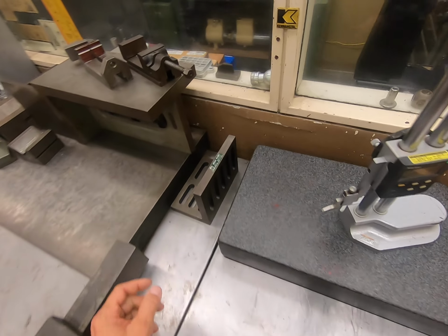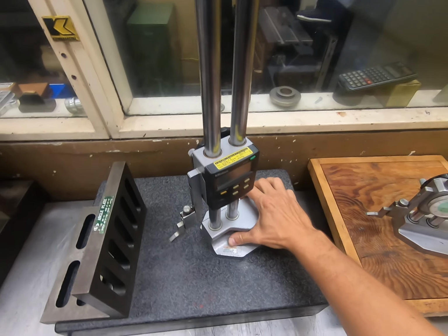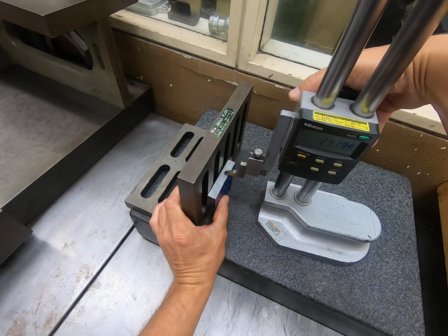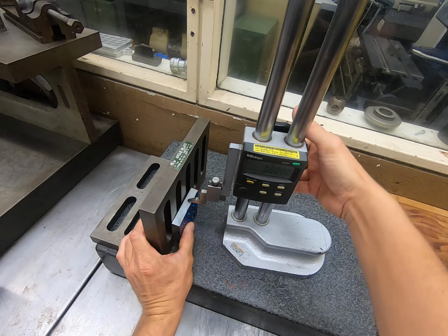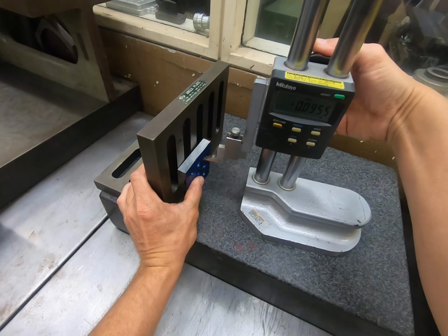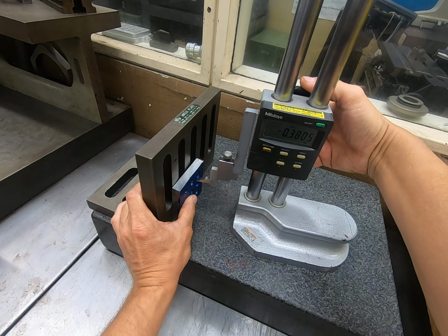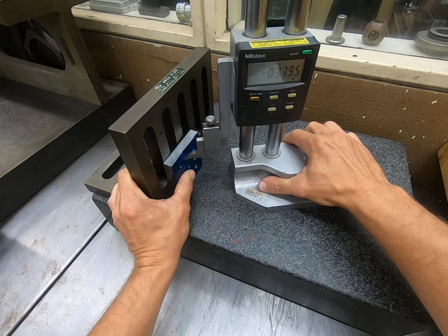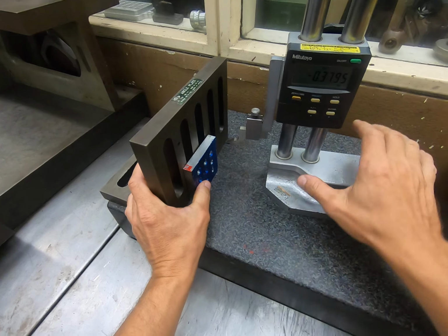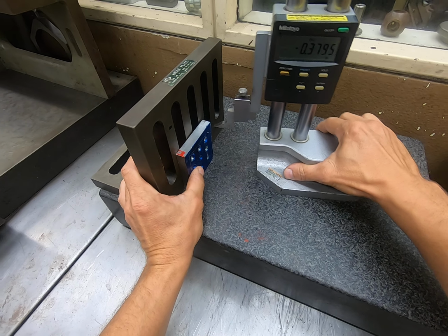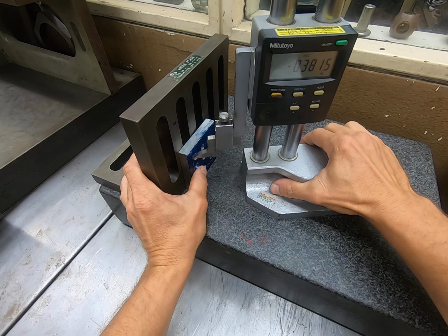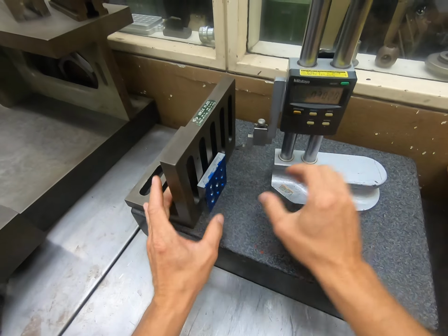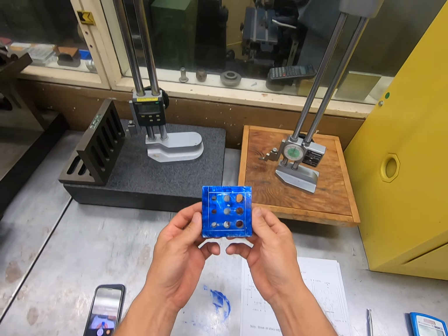So what I'm going to do is put our angle plate up here, and I am going to take our part and the height gauge. We're going to zero right on top of here. We're going to move it down exactly 380 thousandths. And from there, we're going to just scratch it. I'm going to do the old rotation trick here and scratch it 4 times. And now that we're done, we can see a nice square on our part.